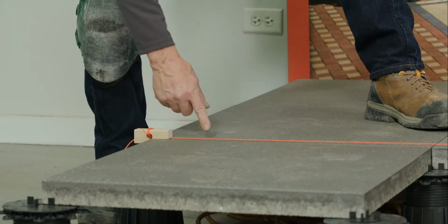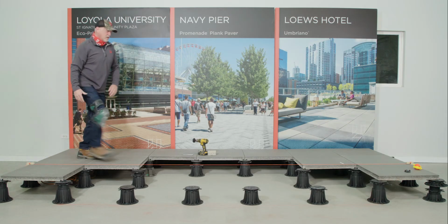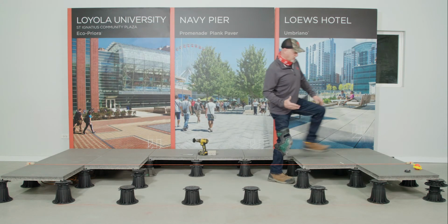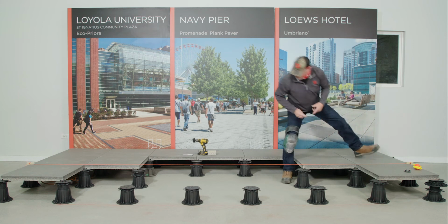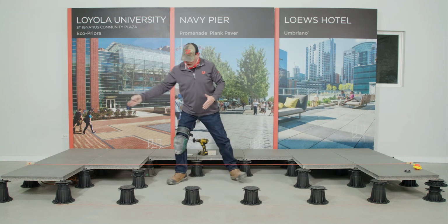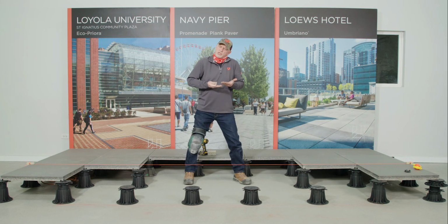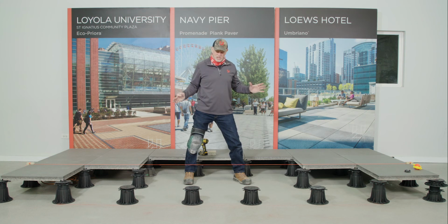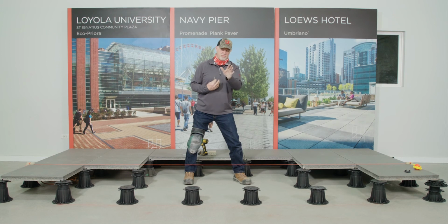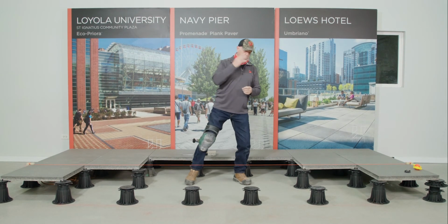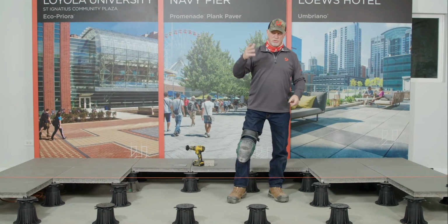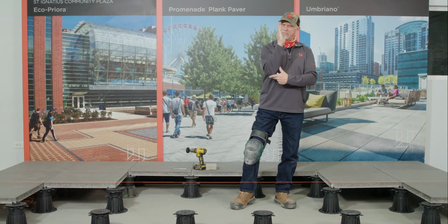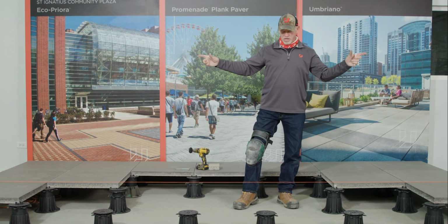Against this edge of that slab. Same thing over here on this far side. I'll make that final adjustment. Now, one thing that dry line is going to do is it'll show a little bit of sag, even with high tension associated to it, over a longer distance of 30 to 40 feet. If you're doing an installation that requires distances further than that, Brad has shown you in the presentation about doing that center point and then working in two directions.